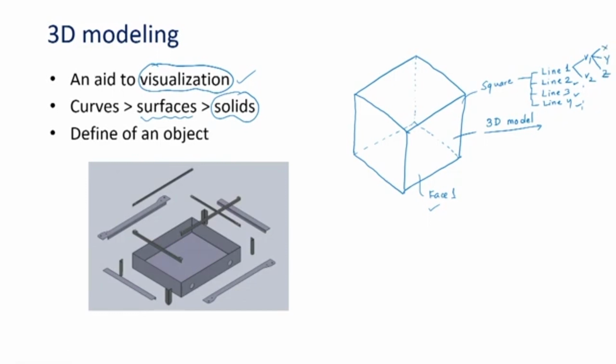If I try to develop an inverted tree, then I can say that we are getting a solid. The solid has faces, so face 1, face 2, and so on and so forth. The faces have boundaries or curves or lines. The most appropriate word is edge, edge 1, edge 2, and whatever the number of edges it has, say n, number of faces are m.